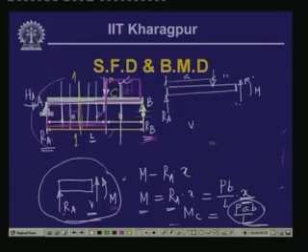that what happens to the value of bending moment from this particular free body diagram. Now, if we take the moment of all the forces with respect to this particular point, let us call this as say D. Now, here the moment m, again the general moment m, which is at this section, is in the anti-clockwise direction. Now, the R A is causing a moment which is in the clockwise direction. So, minus R A into x. Now, load P, which is acting at a distance of a, also is causing a moment which is in the anti-clockwise direction. So, this is plus P.